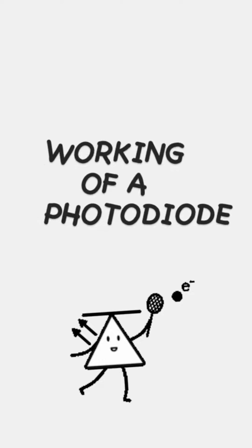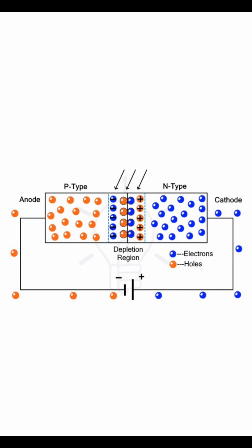Working of a photodiode. So how does the photodiode work? A p-n photodiode is similar to a conventional p-n junction diode. When a p-n junction diode is reverse biased, the depletion region widens. Minority charge carriers are generated that constitute the reverse current of the diode. This reverse current is directly proportional to the applied reverse voltage.